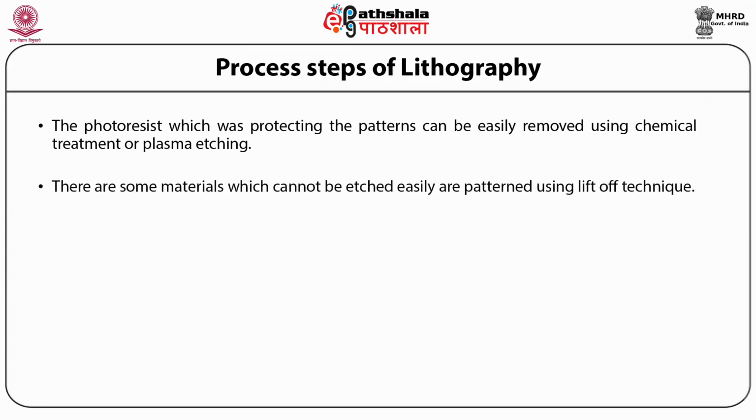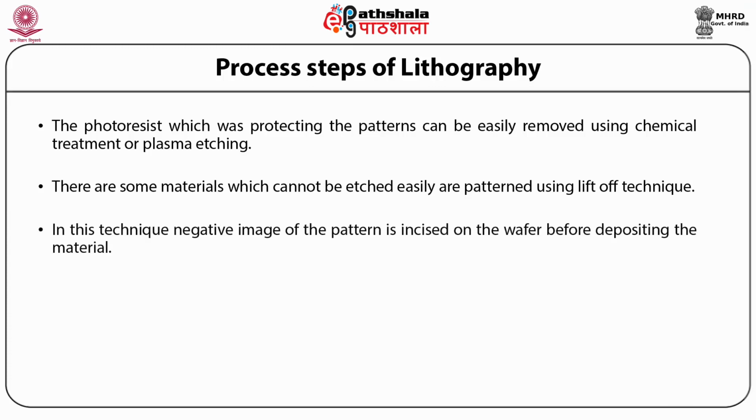There are some materials which cannot be etched easily and are patterned using the liftoff technique. In this technique, the negative image of the pattern is incised on the wafer before depositing the material.